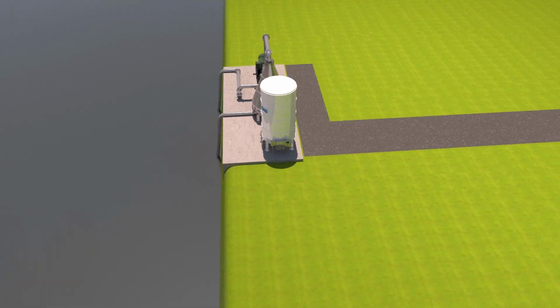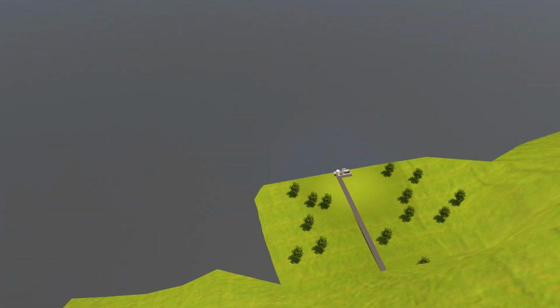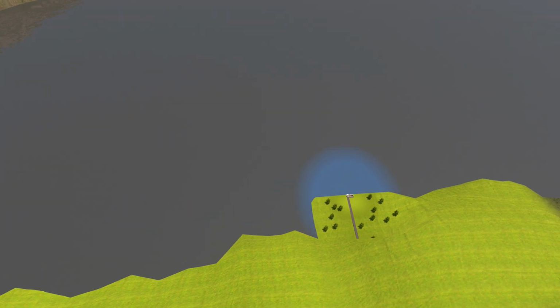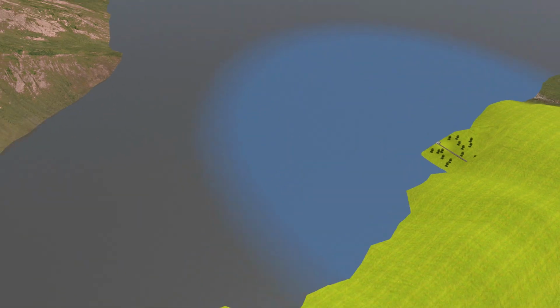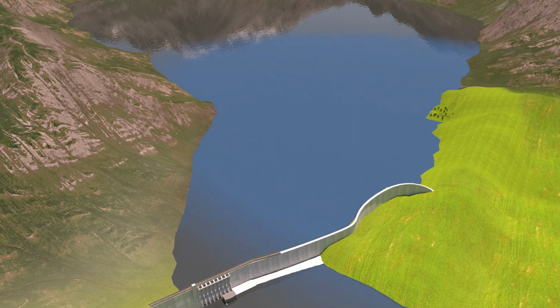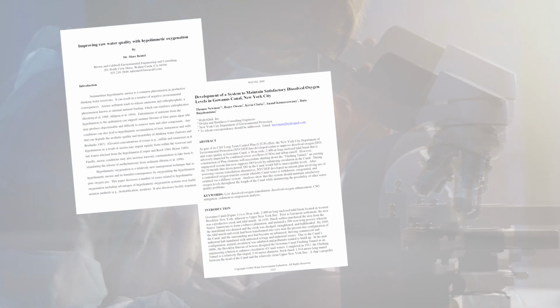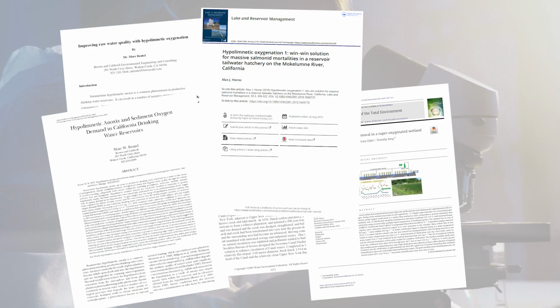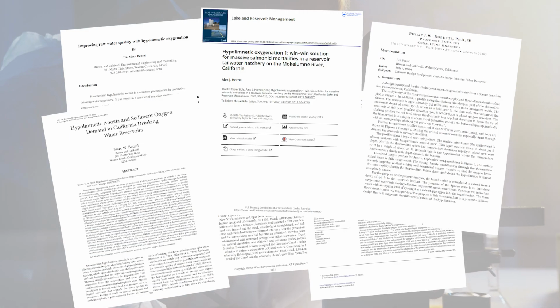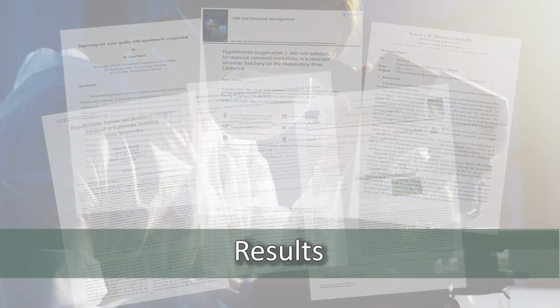As the oxygenated side stream is returned at the same depth as the intake, the low temperature gradient promotes horizontal distribution across a large area of influence. Within 3 weeks, aerobic sediment conditions extend over 3 kilometers from the discharge of the Speece Cone. Over 30 years of field data have been collected, peer-reviewed and validated by leading limnologists, confirming the results of full-scale Speece Cone oxygenation.